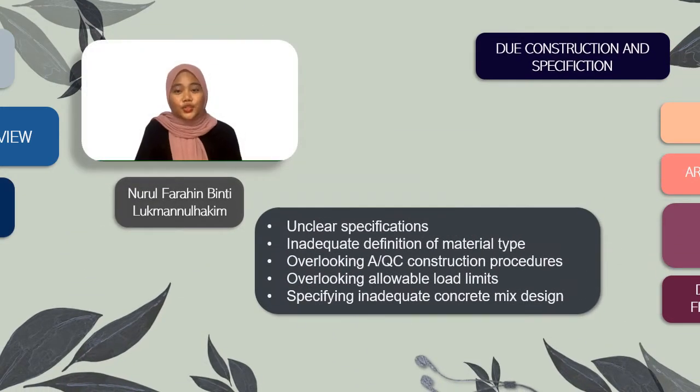Next, defects due to construction specification. First, unclear specification. Inadequate definition of material type, overlooking QA or QC construction procedure. Fourth one, overlooking allowable load limit. The last one, specifying inadequate concrete mix design.